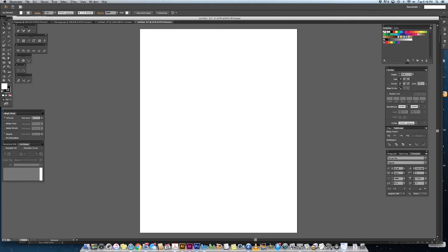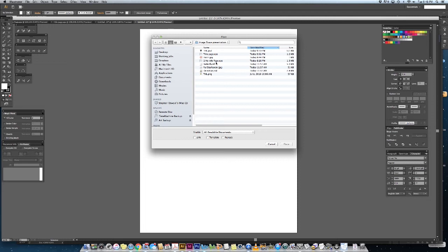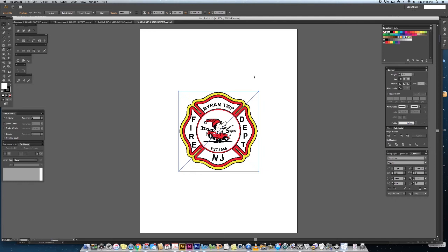As you can see, our control panel changes automatically at the top when we place our raster image. The control panel at the top is a contextual object, meaning it changes based on what's selected out on the artboard. So as I bring in this artwork, keep your eye on the control panel and watch it change and give us the options for image trace. There we go. So I could simply come up here to the image trace tab, choose one of our defaults, 3 color, 6 color, 16, and so on, but none of these fit my needs.